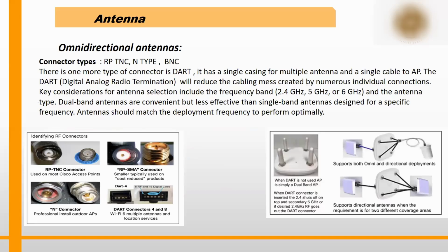So this is the omnidirectional antenna connectors that you can use. Okay. So these are called as TNC connectors. This is the kind of connector that you will use. So when this AC signal is generated by the transmitter and passes through the cable, it also has attenuation. And this is the connector. Okay, just like in the older times, you will be having this dish TV, right? So in that dish TV, you will have some connectors like this. So this connector also will lead to the attenuation, maybe of 1 dB, minus 1 dB or something like that.